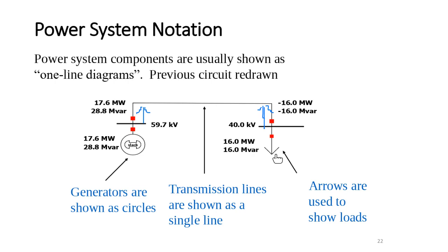When you have a number of buses, just look at each line and at the sending end and the receiving end, then you can calculate the losses. The exam, for example, will give you maybe a 9 bus system, and ask you to calculate maybe the losses in transmission line 5, transmission line 6, etc. Therefore, you will look at the sending end and receiving end.